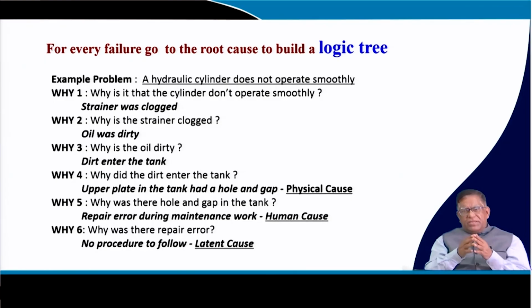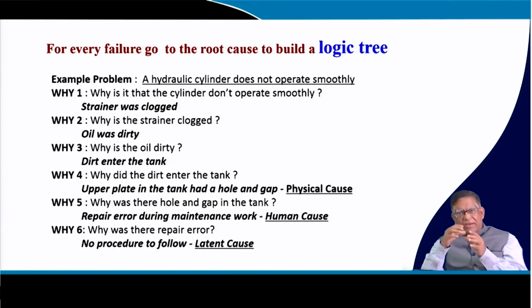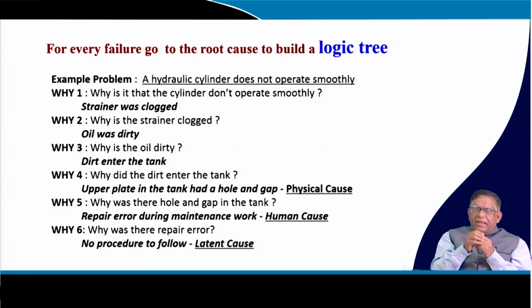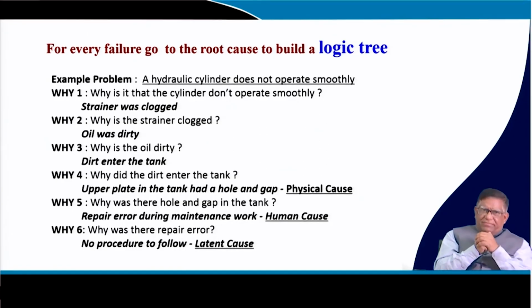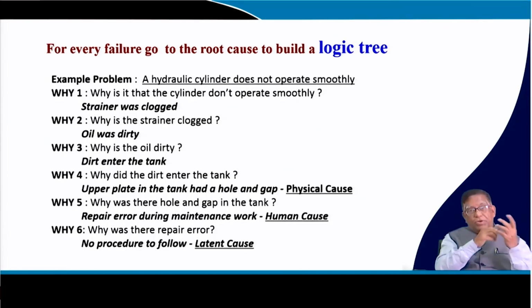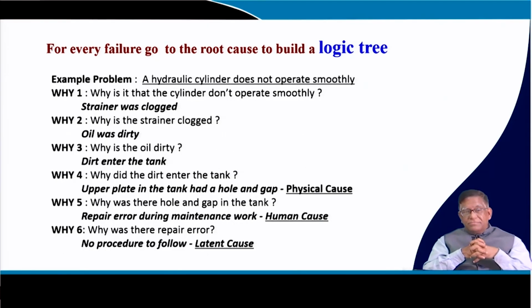Maybe some dust particle has come inside the cylinder, which means the strainer was clogged, somebody may say. Then you will ask why the strainer is clogged. It should not normally clog. A strainer is a screen, as you have learned, with different meshes. Somebody will say, yes, the oil is dirty.